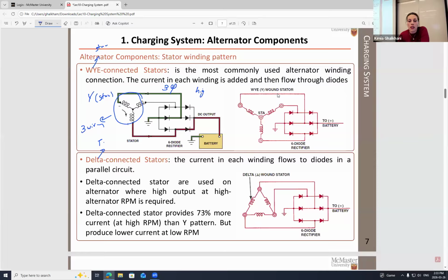I'm going to summarize it in here. We have higher voltage output. This is one of the benefits. Another one is we are going to have a neutral available, while we do not have a neutral for the delta connection. Another factor for the Y connection is that we have less insulation. We do not need too much insulation. So, less insulation. You may want to take your notes or later watch the recording.